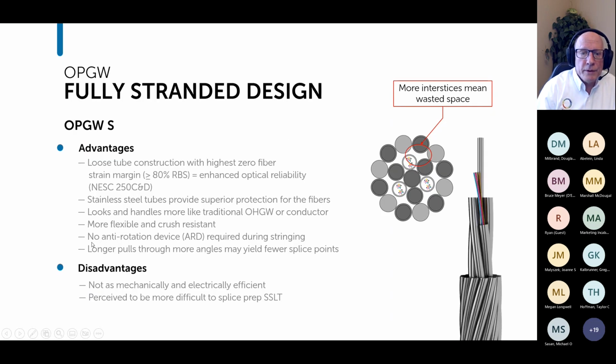Because of this, you generally do not have to use an anti-rotation device for them. Some suppliers will require them, but many do not, including us. That allows you to go longer pulls through more angles and may yield fewer splice points, which save money if you're eliminating splice points. But unfortunately, they still do have some disadvantages.